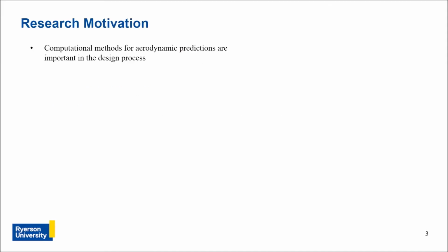So, computational methods form an important part of the aircraft design process. They allow us to quantify the performance of a design without necessarily requiring experimental testing. Broadly speaking, most prediction methods fall into one of two categories. We have "high-fidelity" CFD methods, which discretize the flow field and solve the Navier-Stokes equations across the resulting cells in the control volume. Then there are "low-fidelity" potential flow methods, which often use surface-based singularity representation, and their low cost stems from simplifications to the governing equations. Typically they model the flow field as irrotational, inviscid, and incompressible.